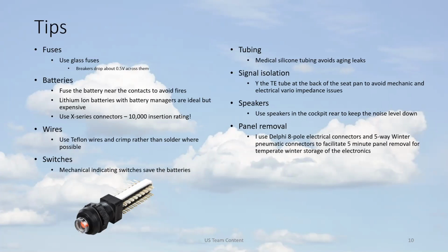I see a lot of people using these little white Molex connectors that quite often are supplied by the glider manufacturers, but if you ever take the time and read the spec on them, they're good for 300 insertions. So basically after 5 years, you've got to take them out, throw them away. So it's better to get something that will last the duration.